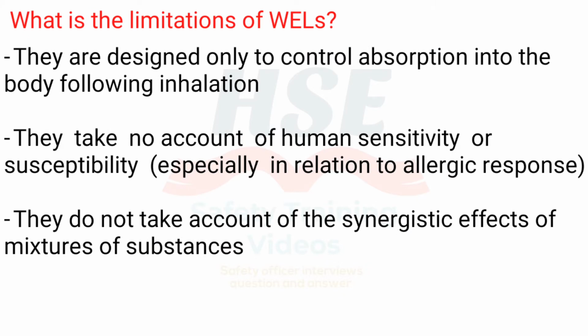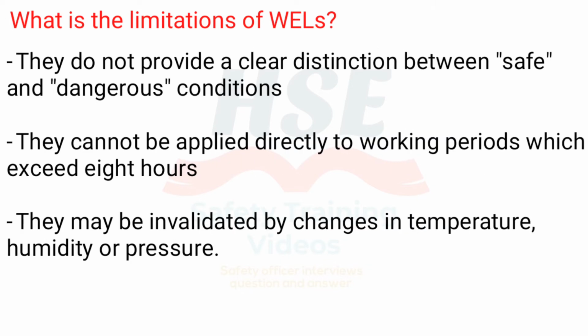What are the limitations of WELs? They are designed only to control absorption into the body following inhalation. They take no account of human sensitivity or susceptibility, especially in relation to allergic response. They do not take account of the synergistic effects of mixtures of substances. They do not provide a clear distinction between safe and dangerous conditions. They cannot be applied directly to working periods which exceed 8 hours. They may be invalidated by changes in temperature, humidity or pressure.